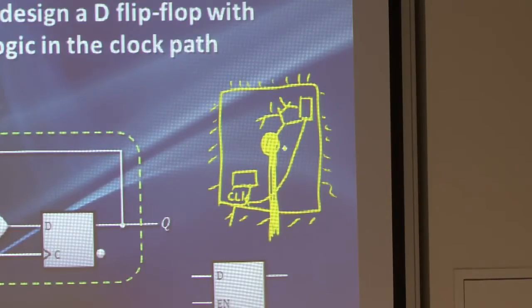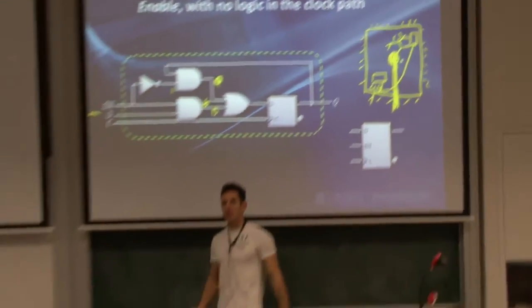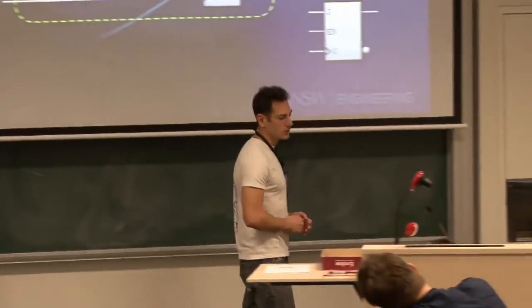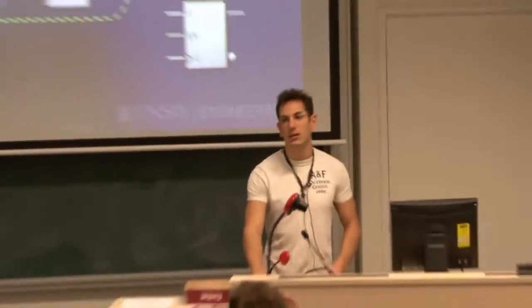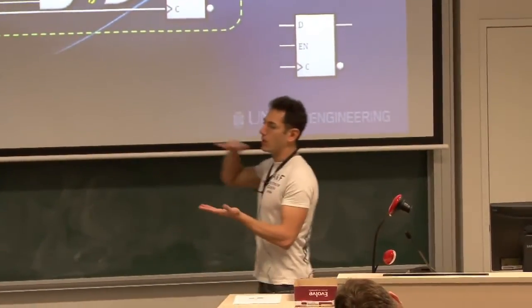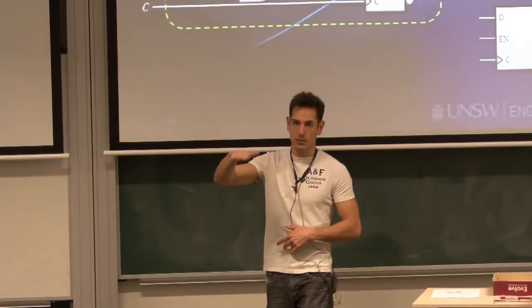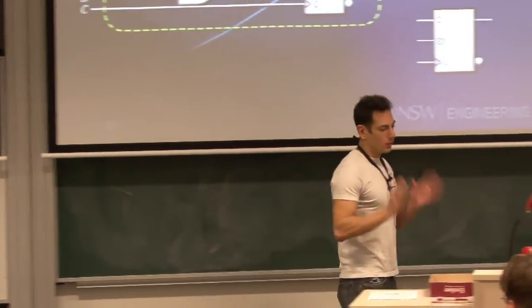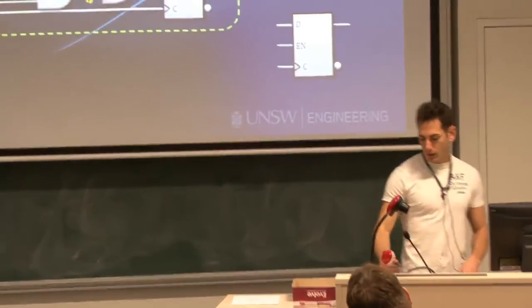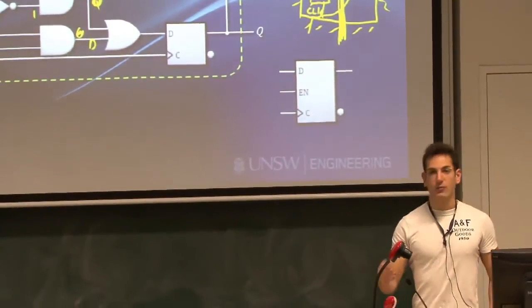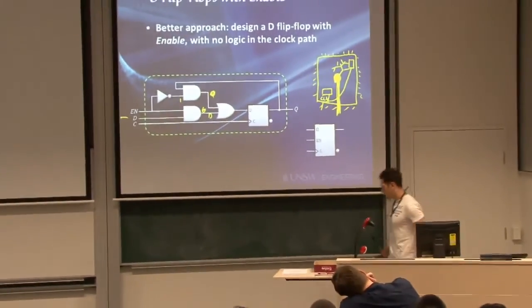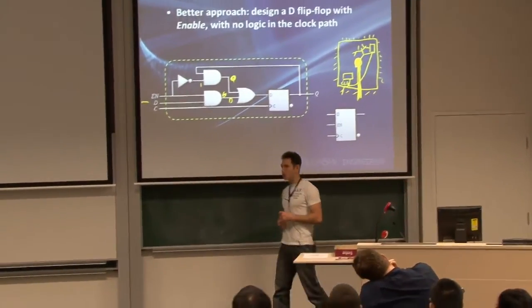One of the main problems for a signal to propagate through is the resistance in the wire. The thinner the wire is, the more resistance you'll have. So just say, all right, I'll make my internal wires thicker. And in today's technology, it's not a problem passing wires because you have different layers on the chip. So you can have, and this is what they do, a layer dedicated to the clock, a layer of metal wires. And you can say, I want my clocking wires to be really, really thick, therefore minimizing the resistance, therefore I will get them propagating faster.